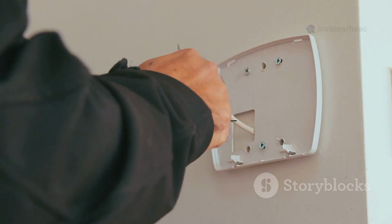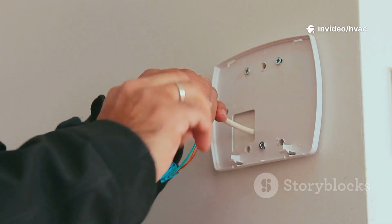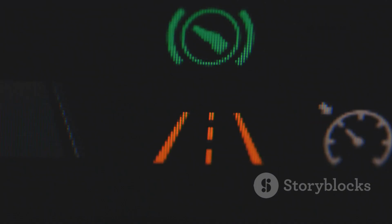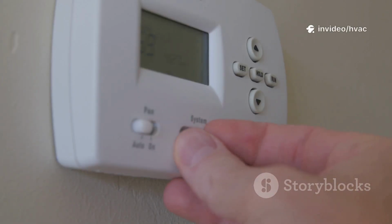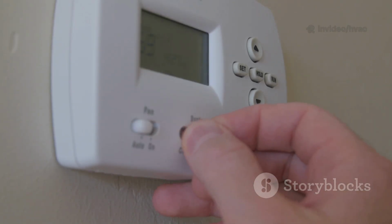If the duct is very large, you may need to use support wires or additional clips to keep the sensor suspended in the airstream. If your duct has bends or changes direction, add a little extra sensor length to cover the full path. For each bend, add about 1-2 feet to your total sensor length to ensure complete coverage. Carefully route the sensor around bends, keeping it as evenly distributed as possible.